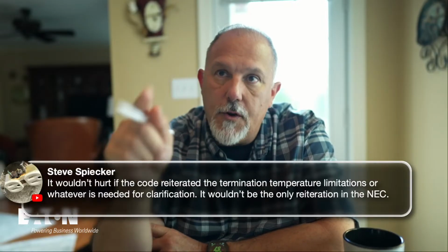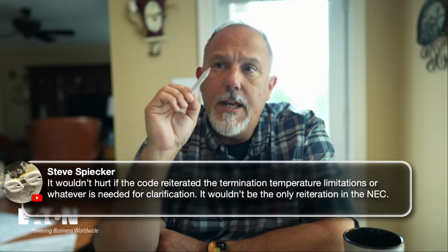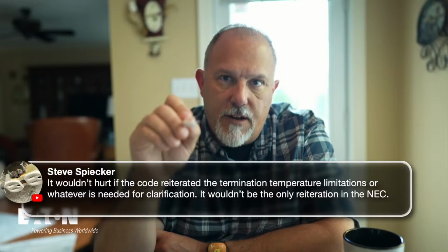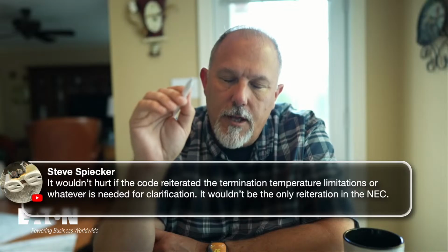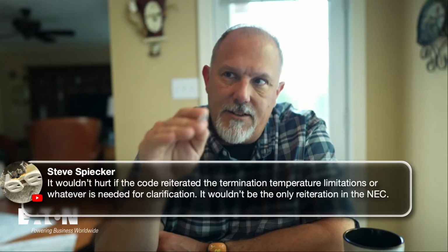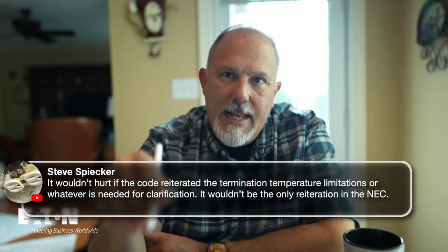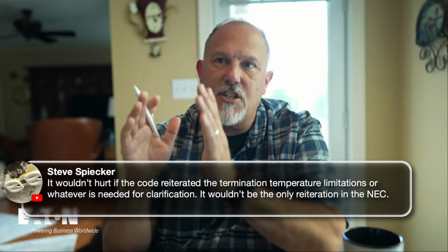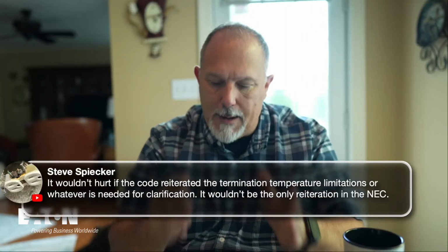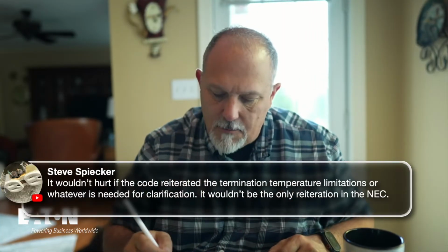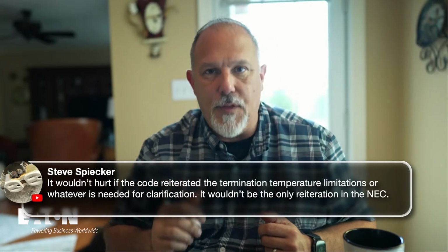So somewhere in 430, and we'll look at the overload, I would go to the overload protection. The overload protection is where I need my 110.14 reference. It would not make sense that I would put a 110.14 reference into this section of the code because this section of the code is just dealing with the conductor selection. And it's telling me what my minimum size is. It doesn't tell me that I'm going to end up using a number 12. It says I can't go less than a number 12.